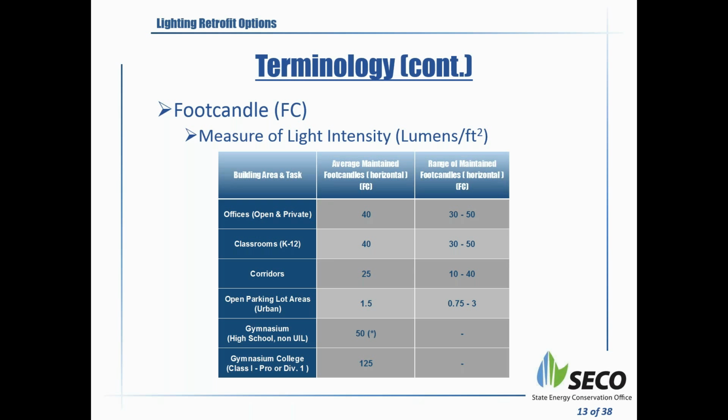I also want to let you all know that there are certain requirements for certain areas, what they call the vertical foot candles. The vertical foot candles will be important in gymnasiums so that you are able to see the object if it is thrown up high in the air. And it is also important in warehouses, so you have to look at both the horizontal foot candles and the vertical foot candles, because in the warehouses you may have aisles, and aisles may have different things stored in them, so you need to be able to see them.